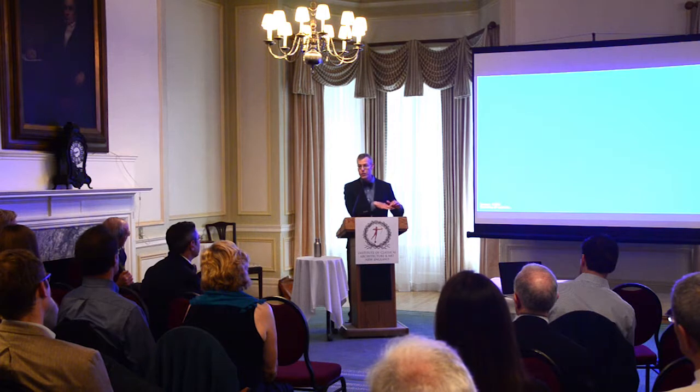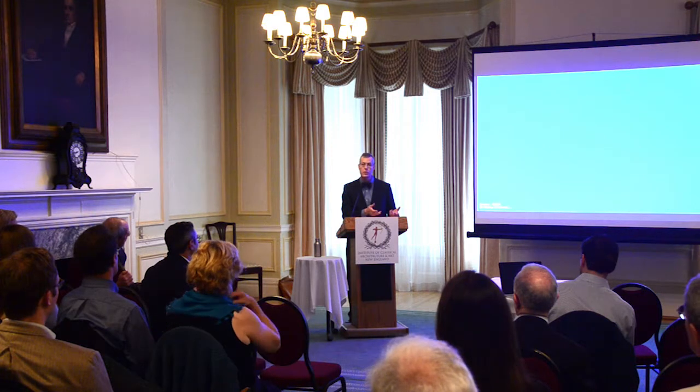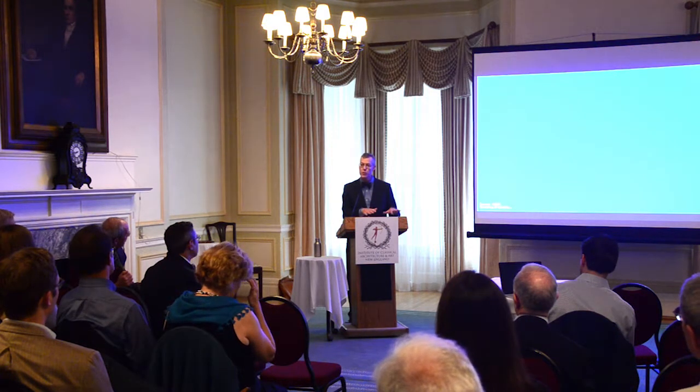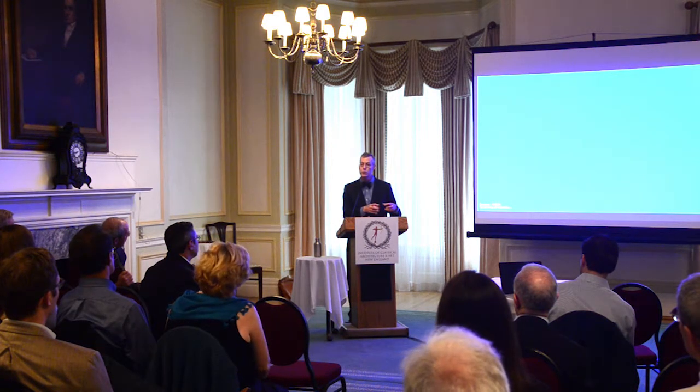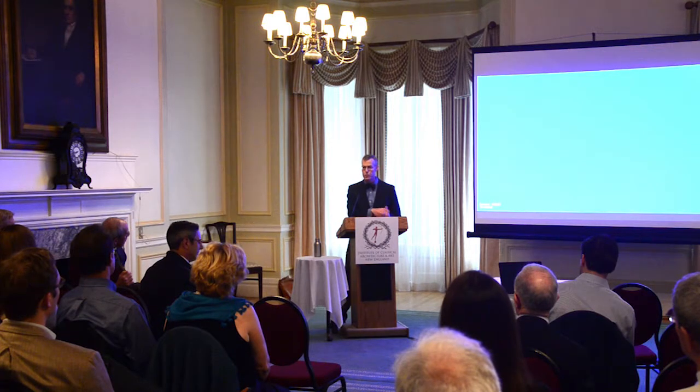Natural pozzolana, which you get all around the central Italian peninsula because of all the volcanic activity from Mount Vesuvius, is essentially a very clayey soil, and then the clay was cooked by the volcanic eruption. So it's very much akin to brick dust in that it's clay that's been vitrified. You can pick that up all over the ground as you're walking along. There are two varieties, a very red and a very black, and that's pozzolana.